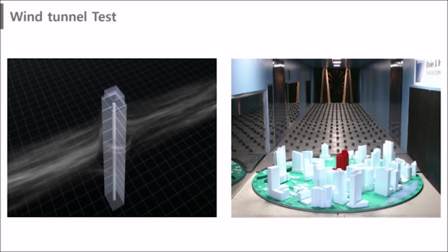Next, I will show you the wind tunnel test. As the wind hits the building, it creates a vortex. And when the building and wind vibrate together, the building shakes greatly. This is the same as when you push your foot against the swing's vibration when you swing, and the swing goes further away.